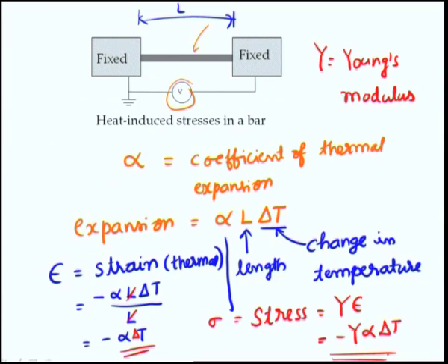We first raise their temperatures, join them together and cool them. When they are cooled, each of them will cool to different extents. That means one will contract to a lower length than the other, because they have different thermal expansion coefficients. When you bring it back to the original temperature, both of them will retain certain residual stress.